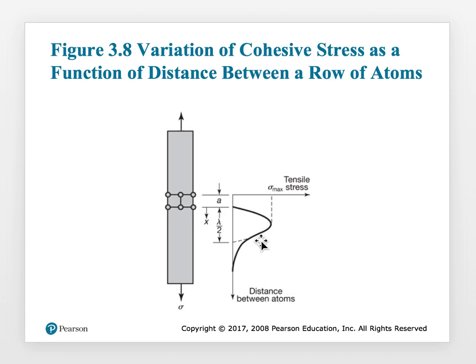So, just to reiterate, slip will happen more easily in the planes where there are maximum number of atoms. Why do I say that? The reason is those planes where there are maximum number of atoms also have the maximum distance between one plane and the next.